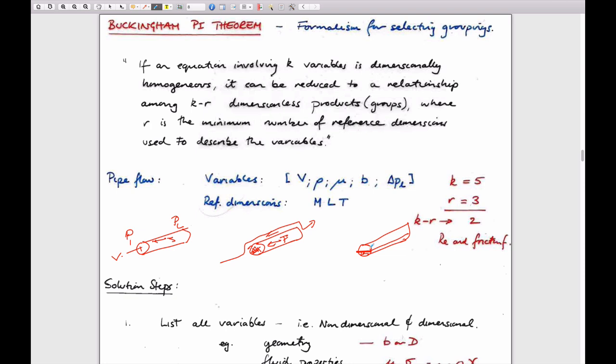And so the only thing that's driving flow in this case is gravity. And gravity, as it would go downhill, will only drive it if it's tilted. And also there'd be a shear stress acting on this due to gravity. And this shear stress will be resisting flow. It means it won't go at infinite speed for a very small gradient. And so this drag on it will actually condition the flow velocity within the pipe, which is the essence of free surface flows.